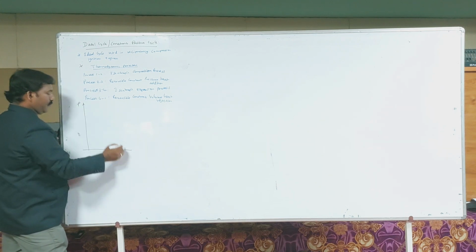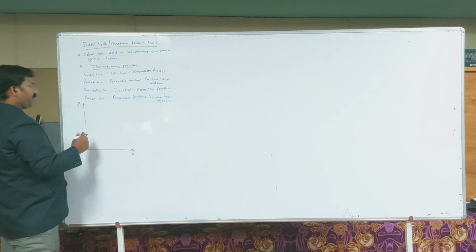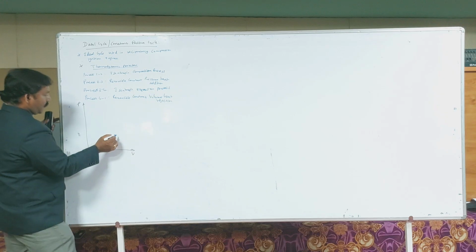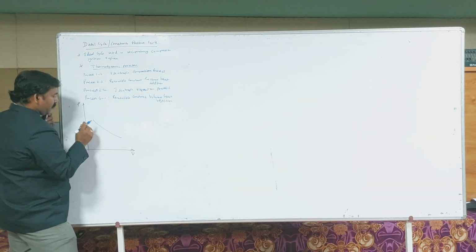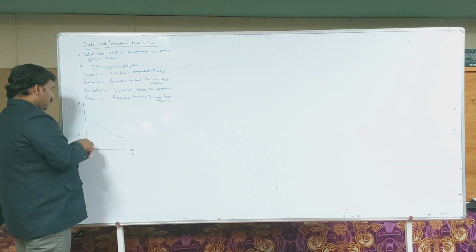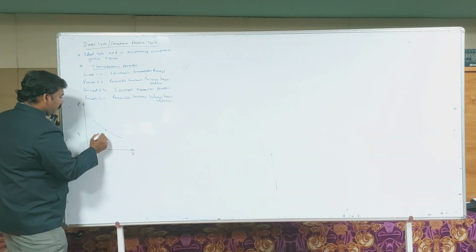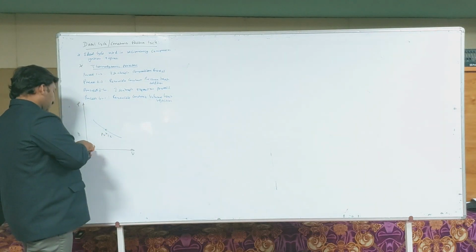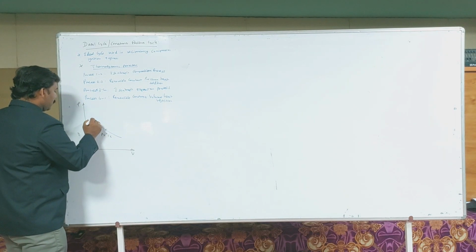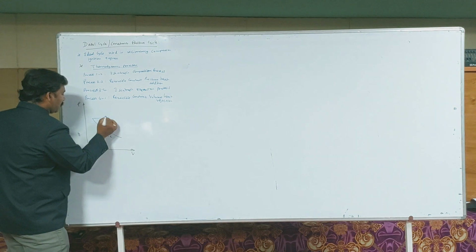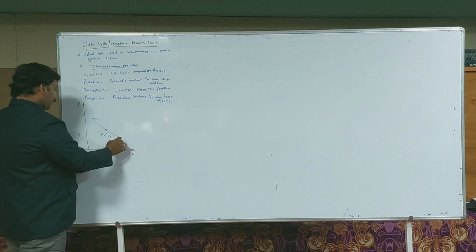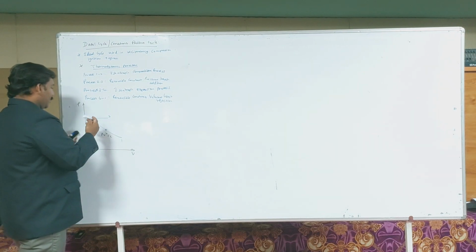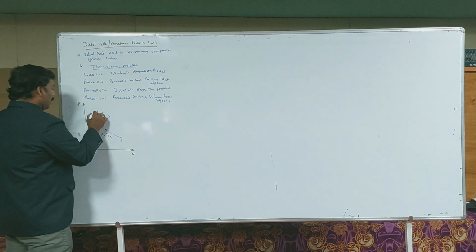So this is the PV diagram for a diesel engine. The 1 to 2 is an isentropic compression process, PV power gamma is equal to constant, and after compression the heat is added at constant pressure. Process 2 to 3 is a constant pressure heat addition.